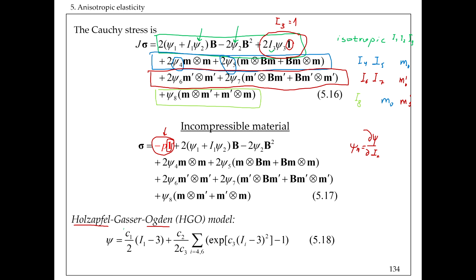And as you can see, this is the approach that was also taken for the isotropic part. So this is just one invariant, I1. And I2, again, we already mentioned that it's quite common to neglect that and limit ourselves to a simpler model. So basically we have for the isotropic part only the first invariant, pretty much like a Neo-Hookean model.